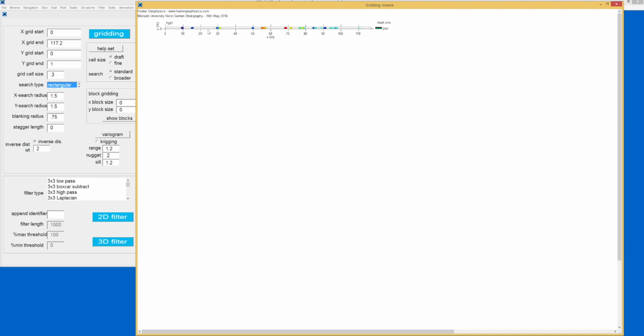There are gaps in between each individual reflector in our depth slice, or it's not a depth slice anymore, it's a map of the amplitude solely for the hyperbolas that we've detected. In this case, they're probably just buried rocks, or buried surfaces. But if you had reinforcing bar, you'd be able to see a map.